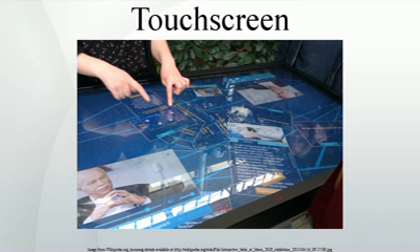Self-capacitance. Self-capacitance sensors can have the same XY grid as mutual capacitance sensors, but the columns and rows operate independently. With self-capacitance, the capacitive load of a finger is measured on each column or row electrode by a current meter. This method produces a stronger signal than mutual capacitance, but it is unable to resolve accurately more than one finger, which results in ghosting, or misplaced location sensing.